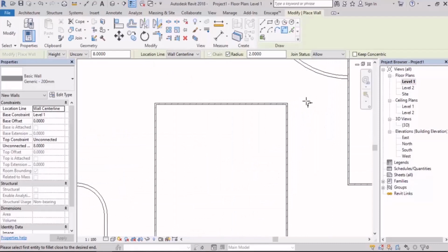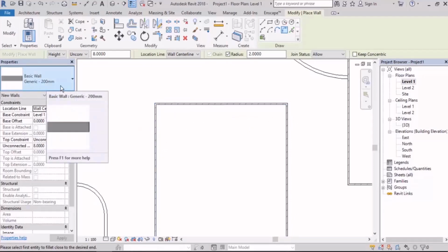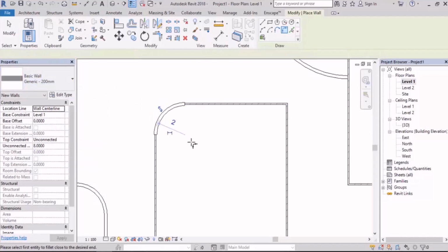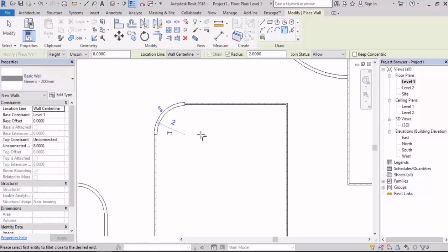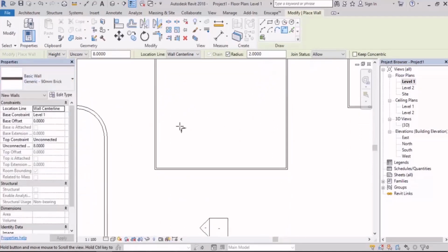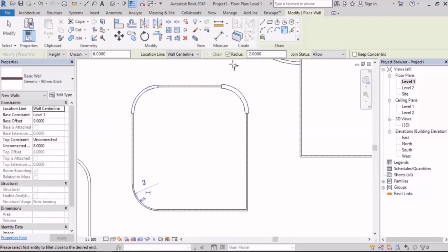But, as I told you, fillet itself is a new wall. For example, these walls you see are thin walls. This wall I want to draw now is 20 centimeters, and when I make these two fillets, that's how it becomes. You see, a new wall is made, not the previous one. And I can also change it and put it on 30 centimeters, and that's how it becomes. So don't believe that the previous walls are edited; the new walls are created with the radius that we need and we want.